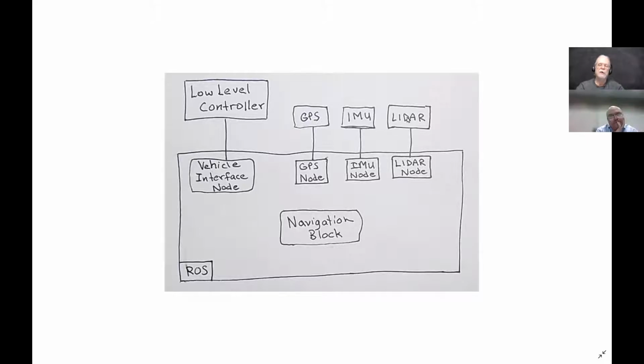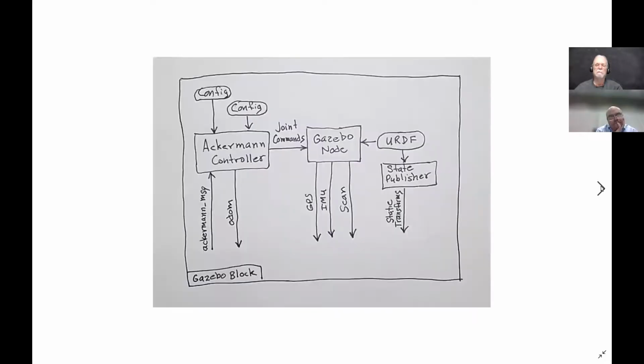And if they don't match, it nudges your position around a little bit to keep you lined up. I don't think you ever know exactly where you are. You know approximately where you are based on that. So if you're running inside of a building, you also start up AMCL. I've got a later slide where I'll talk about that a little more.